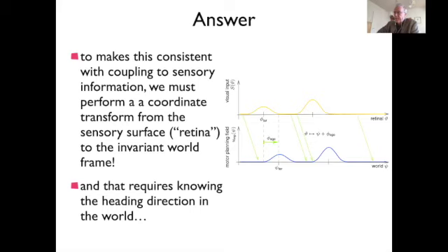So that can be done. It is actually not a stable thing. That is, if you make an error, for instance, you have a slightly wrong estimate of your vehicle size, or your wheels slipped over the ground, and therefore, even though you gave this command to the wheels to turn that much, your actual turn in the world was a bit different. You're not going to recover that. It's nothing that resets that, and that's something that actually can be treated. There's a so-called SLAM, self-localization and map formation problem, which is about using sensor information to recalibrate variables like that.